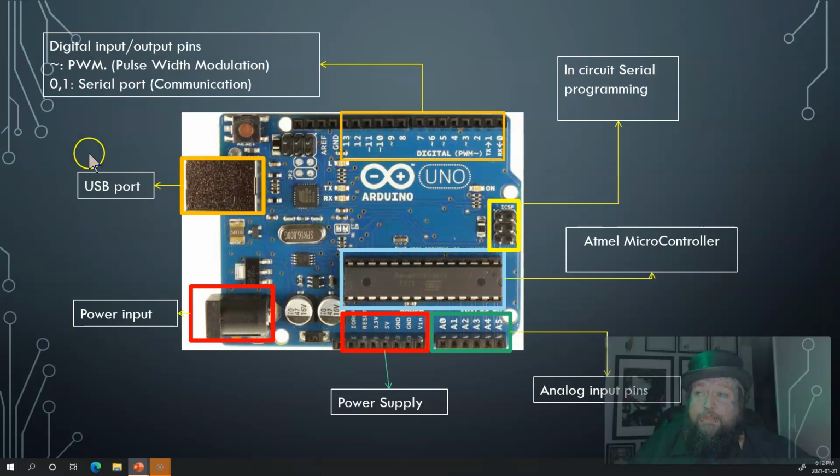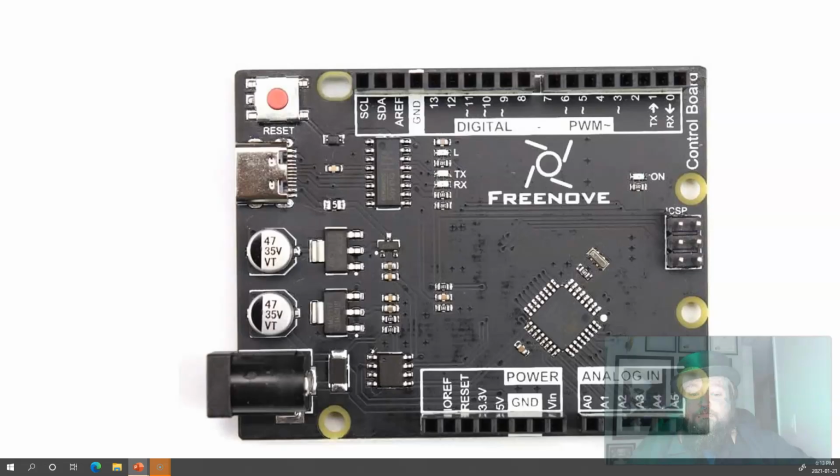Or you can use the power that USB does provide, which is 5 volts, I think around 1 amp or so, to run the overall device itself. So when we're starting this, it'll generally be the USB port here that we're using for power to run everything. But in the future, if you're putting this into some other device, you can use these cases. I'll show examples in the future of all of it, so you don't need to understand everything perfectly here. As we work with the device, I'll be going through more and more of these actual examples.